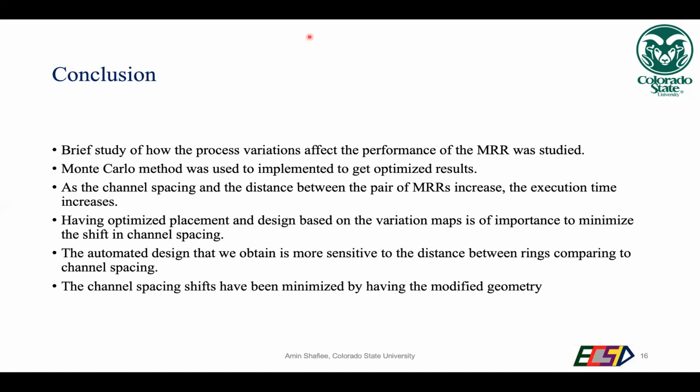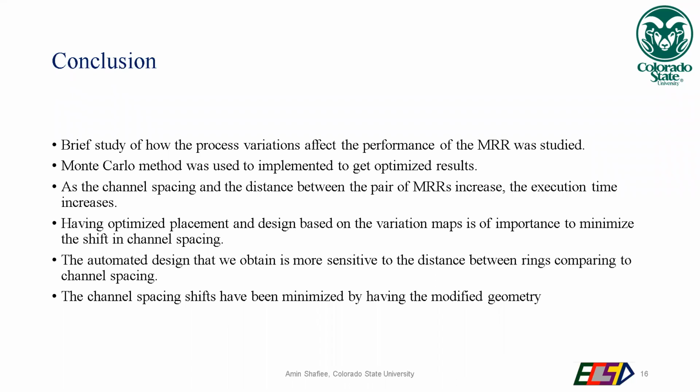So, conclusions based on the methodology we used and the simulation results we saw: we studied that the process variations affect the overall performance of the MRRs, and observed that the Monte Carlo method, though it is time consuming, gives almost accurate results. As for the variation effects, we observed that as the channel spacing and the distance between the pair of MRRs increased, the execution time increases.